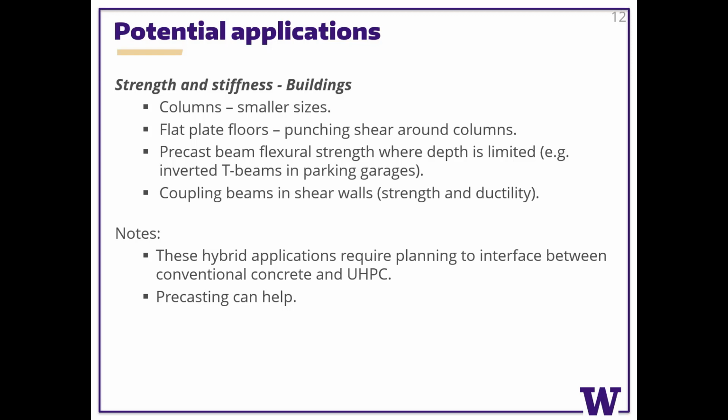Now, some of these things would mean that we would be interfacing UHPC with conventional concrete. And while we've seen in the past 3 modules that it's perfectly possible to do that in the lab, out in practice, it may require some fairly careful planning in order to work out how you're going to interface those 2 materials together.